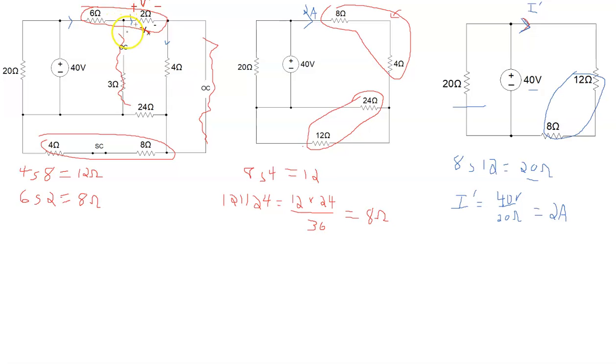The reason we want to talk about that is that back in the original circuit, V prime is equal to I prime times R, which is 2 ohms. And the current enters the positive end of the resistor, so the direction of current and the polarity marked for V or V prime agrees.